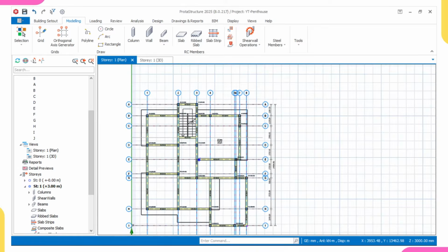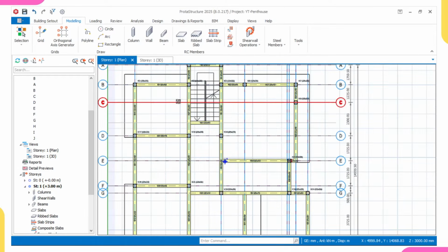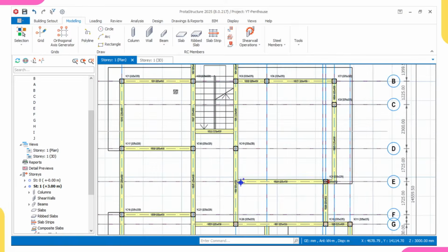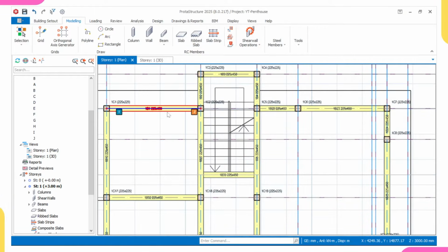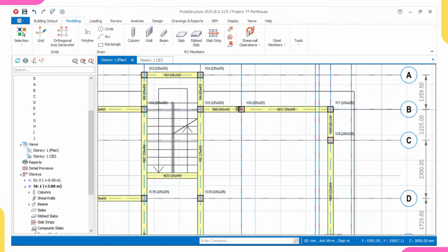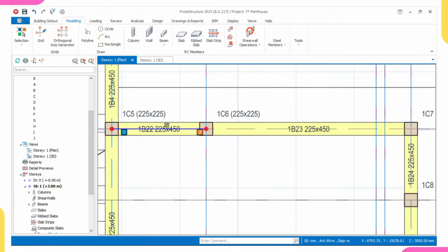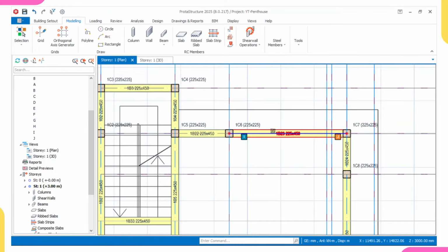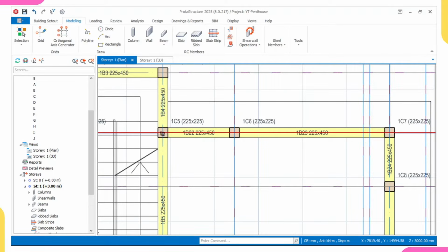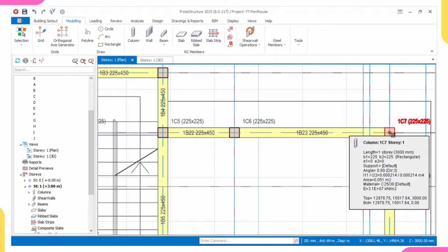Then let's continue. What I would like to explain now is the concept of hinging of beams. Please listen and understand everything. Remember, if we were to draw the bending moment diagram of this beam now, starting from this point, it will come over here. We're having a sagging moment. It will go up, we're having a hogging moment. It will come down, we're having a sagging moment, and it terminates at this point.